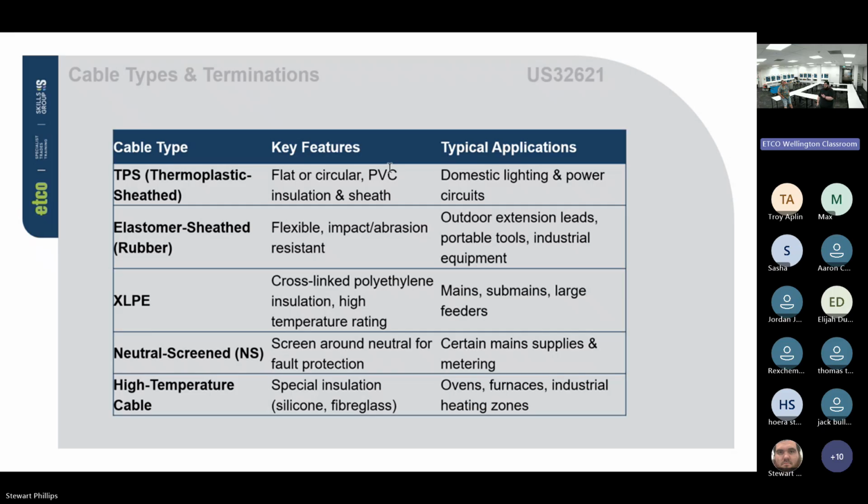Lube, more like lube, not glue. And you really need to kind of work it around onto the aluminium to make sure it gets across all of it. Because if you don't wiggle it around, you'll end up with some spots that don't have any anti-oxidizing compound on it. And that's where you'll get that high resistance joint from the oxidization.